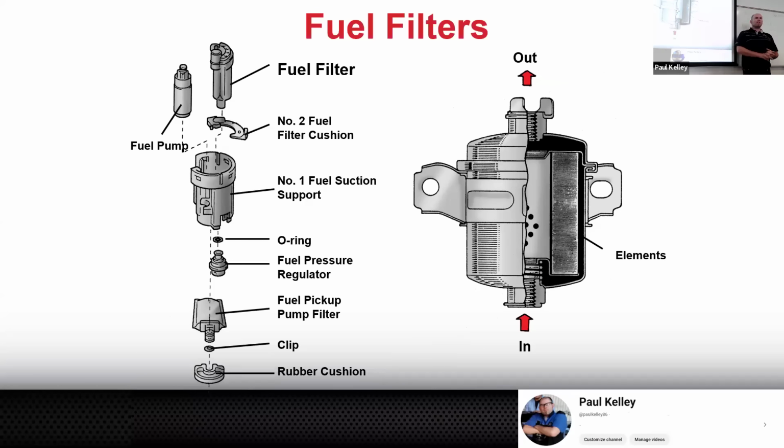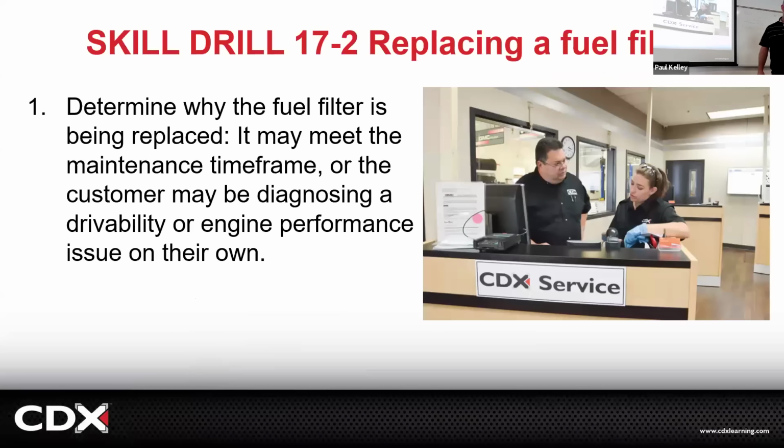But if you're in more of a fleet application, specifically with diesels, a lot of times they'll have a spin-on filter that's real easy to do, and they'll be doing those a lot more often because diesel tends to have even more sediment in it, right? So this is really a gasoline filter. The diesel ones tend to be bigger and spin-ons, kind of nice. But similar, they have media in there.